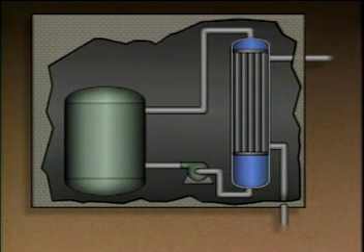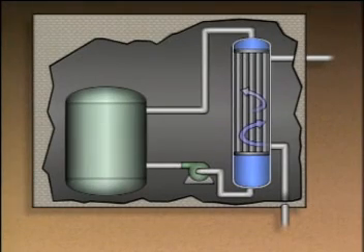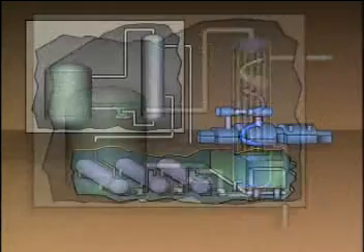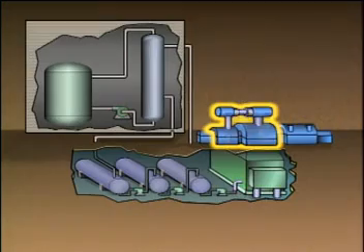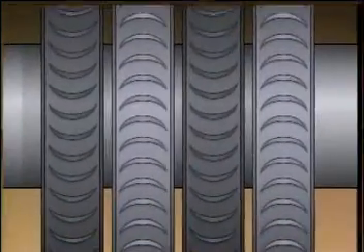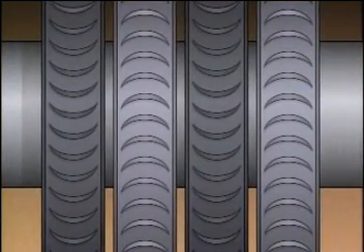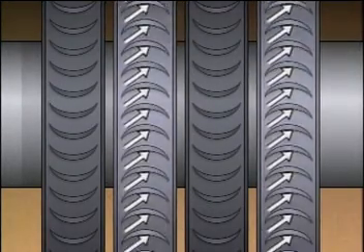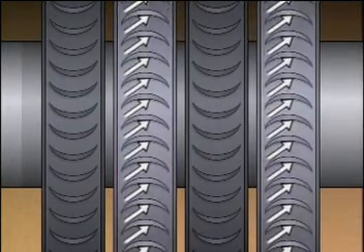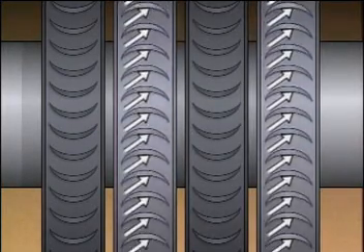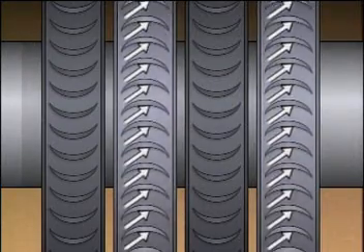What do you think happens to the lower pressure water? When the lower pressure water receives heat, it boils and changes into steam. The steam that is produced in the steam generator is directed to the turbine. The turbine uses blades, both stationary blades and rotating blades, to produce mechanical energy. When the steam hits the rotating blades, it causes them to move, turning the turbine shaft. Some of the energy in the steam is thus converted into mechanical energy.